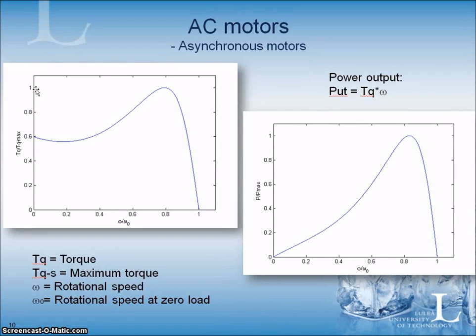And this is important to know if you are using this motor in a machine that you are designing, because even if the torque is given for the specific motor, you have to be sure that it has enough torque when it starts up, especially if you have a system that needs a high torque in the beginning of the motion.